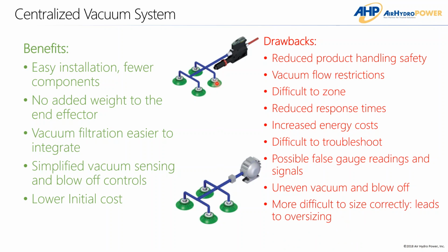And I mentioned this before, more difficult to size correctly. So once again, whether it's taking into consideration leaks or evacuating all this volume, the tendency is to make sure that you oversize the system so that you aren't running at your maximum capacity all the time.